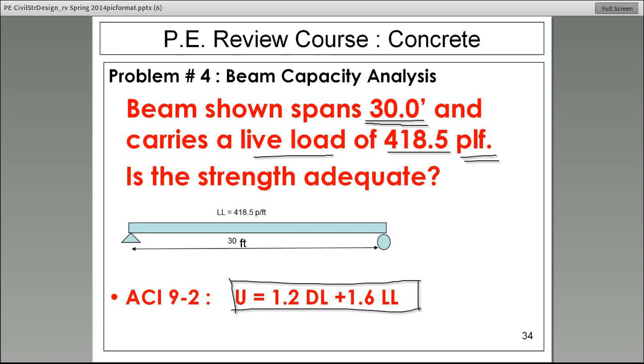And when they leave, the building is no longer subjected to those loads. So that's live load. Dead load, however, is the load that's sustained throughout the life of the structure. And definitely, one big part of a dead load is the materials themselves, the structural materials themselves.